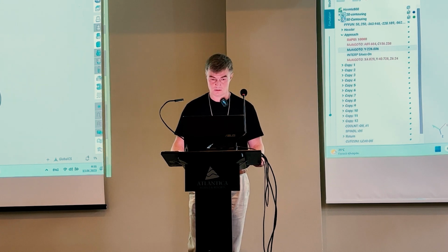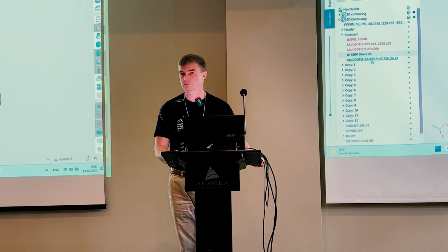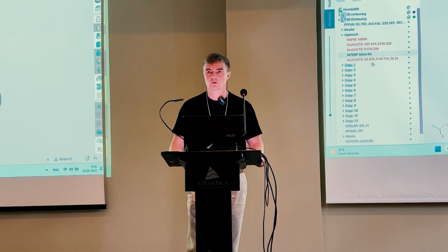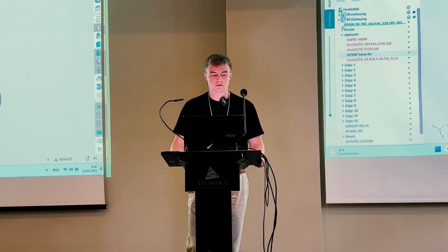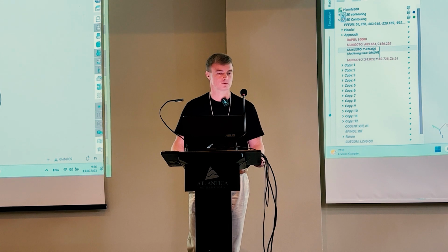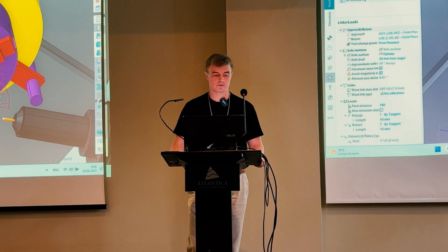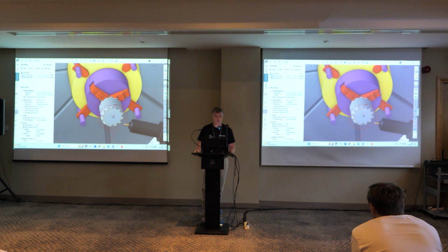And after that there is the command that enables the TCPM mode. So if you know, TCPM mode is activated, for example, by command M128 for Heidenhain, TRAORI for Sinumerik, G43.2 for Fanuc. I hope you understand it. Yes, and I would like to avoid this coordinate, and what I have to do, I go to machining, open the approach rule, and here is the approach rule for my operation. I delete it and input the new rule.